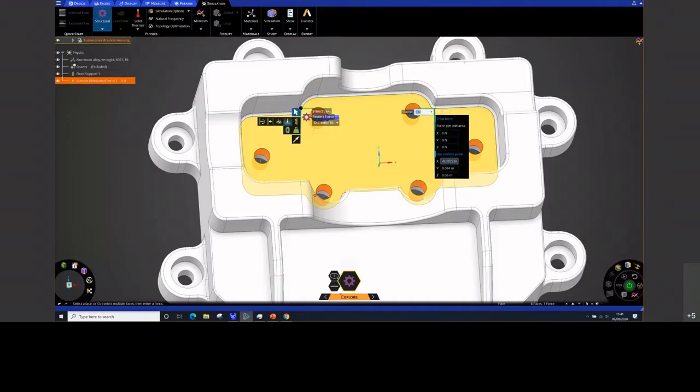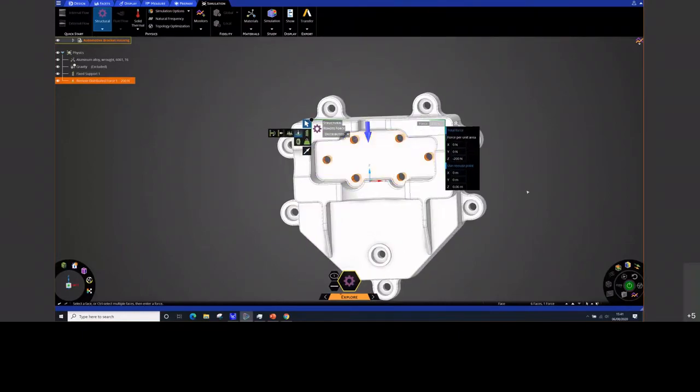So I only want the force in the Z direction, because I know that's where the force is going to be applied. So I'm going to make sure the X and the Y are both set to 0. And obviously Z can stay as it is. And then the force that I want in the Z direction is going to be minus 200. It's going down. The Z direction is going down. And then I can hit the enter button, and that'll apply that force. And hopefully you can see now the force is going in the Z direction, obviously in the minus direction. Again, once we're happy with that, we can hit the escape key twice.